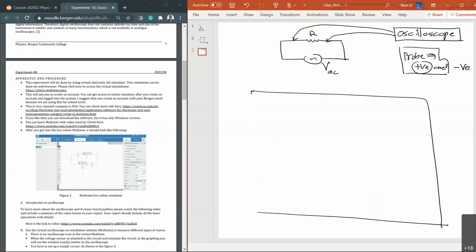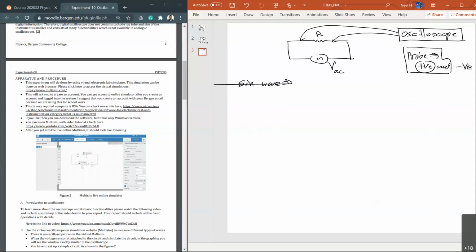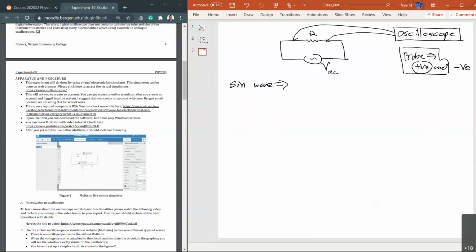Let's write that part down here. Okay, so now we're expecting to see that sine wave, right? That's the idea. But immediately after you connect this, you won't see that at all, or maybe the wave is continuously moving. Then the number one important thing is the trigger.